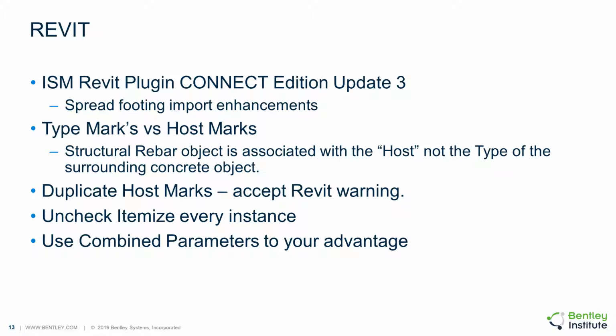We do that pretty much with a workaround using duplicate host names. Okay, and we'll see shortly how that's done. And you want to accept the Revit warning that's telling you that you have duplicate host names.